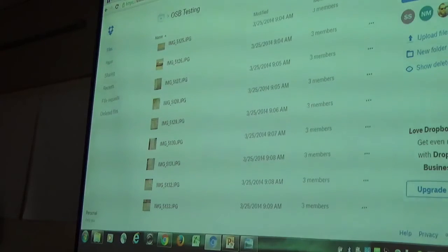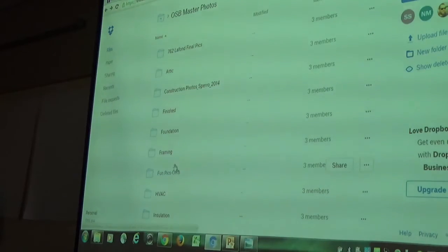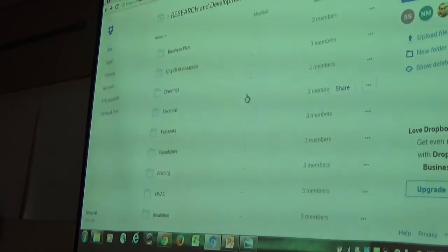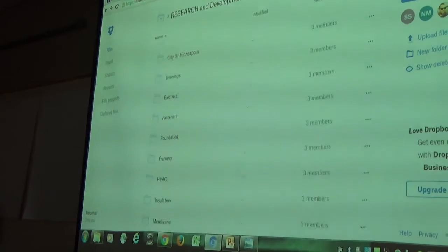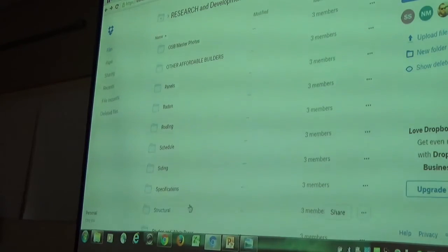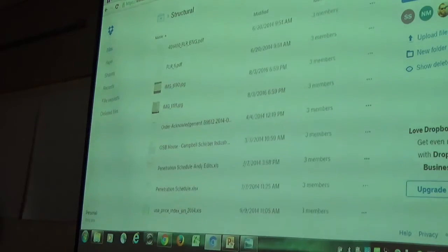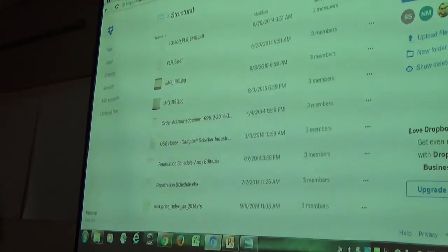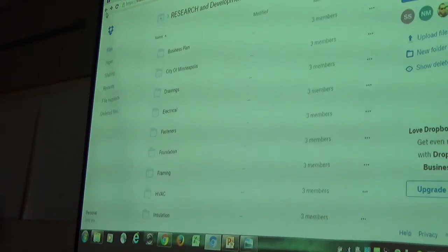When we're comparing it to our typical 2x4 or 2x6 framed wall, I'm also thinking about, it draws some parallels to advanced framing that some of you have probably seen, where you're pulling out any of the redundant pieces. But in order to do that, you have to understand what each piece is doing. And there's pieces in advanced framing that are part of the lateral wind resisting system that I'd be willing to bet some engineers don't even understand the role of each piece. But we've been building that way for so long that we ought to just leave it in there and not change anything is kind of the mentality.